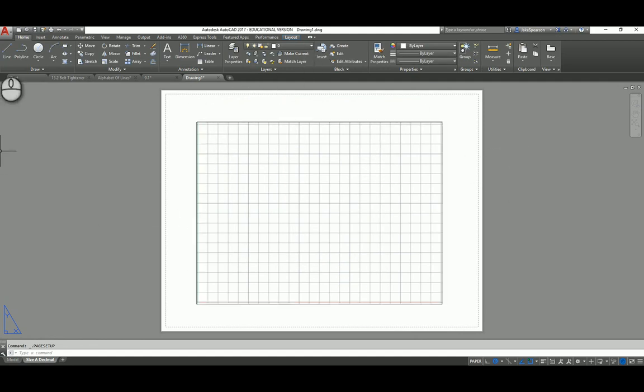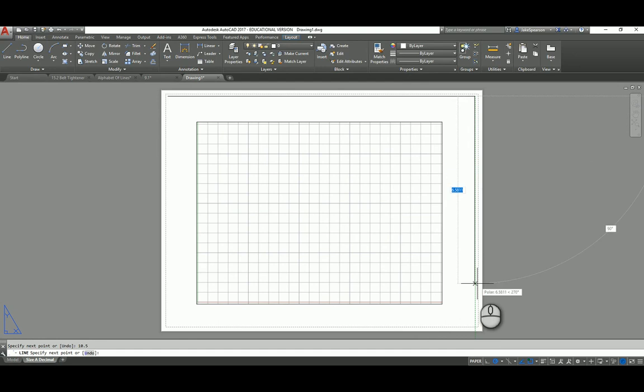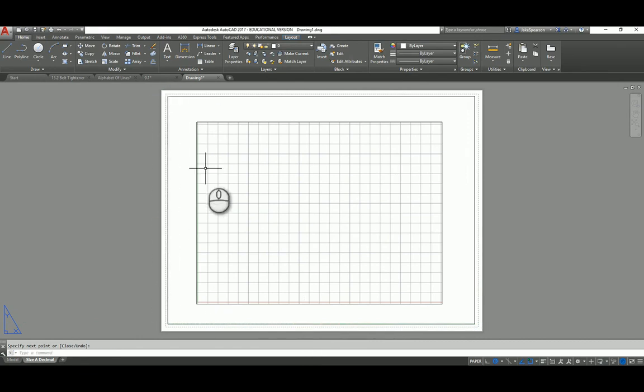What I'm going to do then is simply draw some lines, and I know that I am supposed to be 10.5 across by 8 all the way down, 10.5 over again. Command skill here is I'm going to type in offset, and I'm going to simply bring that line up. Notice, if I don't really want to, I don't have to type out the entire word, because this is a command that I use quite a bit. And I will just simply type in what it should be, which is 3/8. I'll grab it, pull it up. And now I'm going to type in a line.